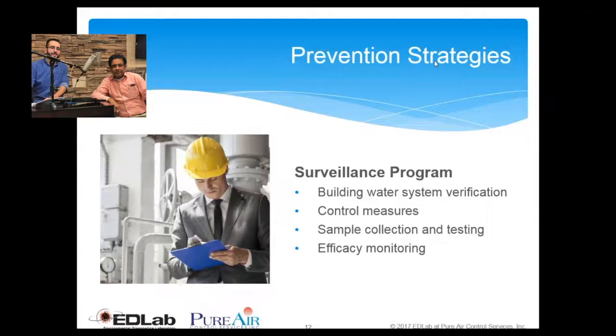And then sample collection and testing is a very important, and I would say essential, step in order to ascertain that the water flowing through the water system is free from Legionella bacteria. So this is the importance of the surveillance program, and that's why it should be done on a periodical basis.